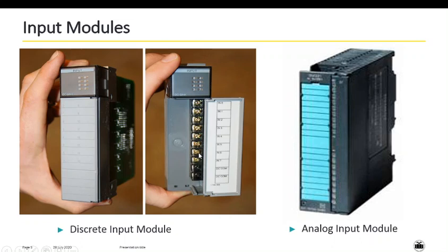These relays are different from electromechanical relays. Just understand the difference between the PLC relays, which are solid state relays, and the old normal electromechanical relay. We have already seen the advantages of these solid state relays in the previous lecture. I will also show what is inside the circuit of this card. Like this, the input cards are there, and this is an analog input module.